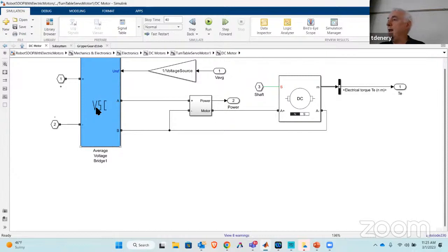But what we're doing is actually way more complex than that, right? Because we're not really going to change it to 7.3 volts for 1/10,000th of a second. What we're going to do is, for that 1/10,000th of a second, hold for 73% of the time if my DC source is 10, and that's what we call pulse width modulation, which is the average over that time.